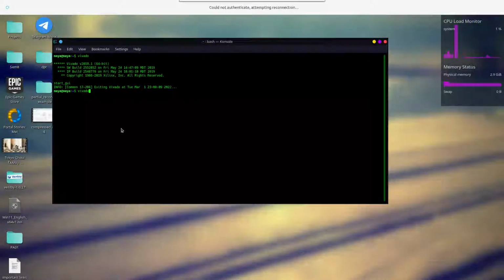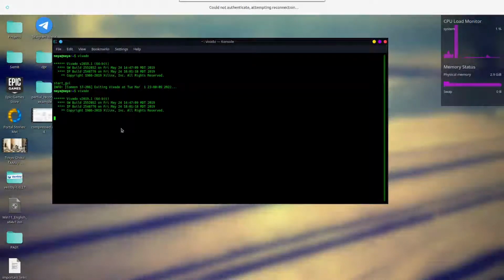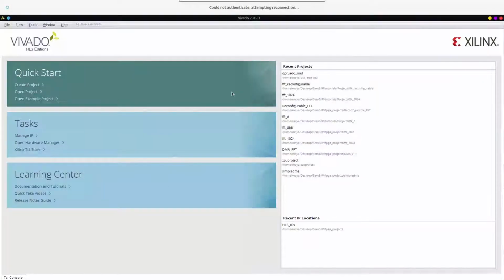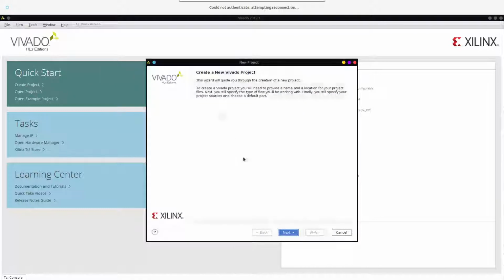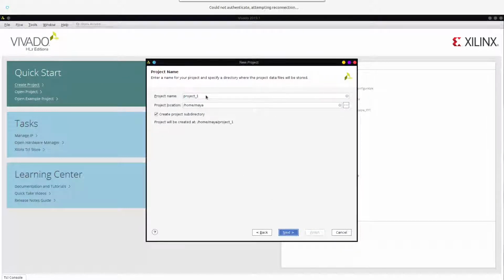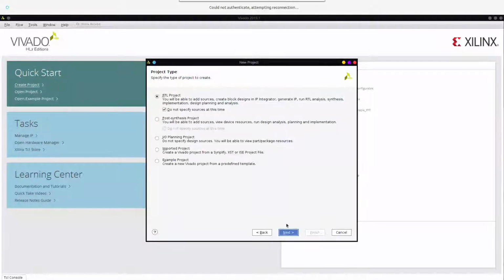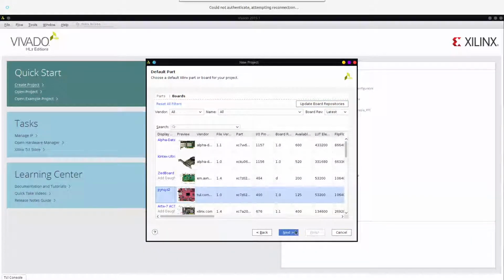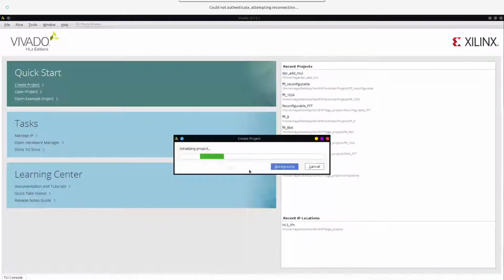This is going to be a small tutorial over the 8-point FFT and the 1024-point FFT, and we will be seeing how this Pynq workflow is different from the SDK workflow that we are working with. So let's just start by creating a new project. I will just name it FFT_8, and do not include sources, and in the boards I will be selecting the Pynq-Z2 board and finish.